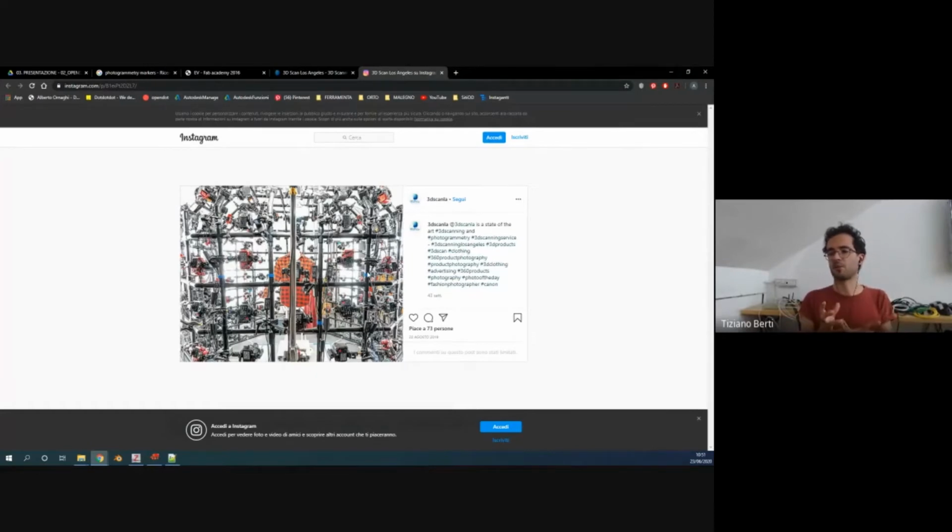If you have an object that is always in the same position while you're doing your photos, it will be much better. Because if you have any tiny movement in the person while doing the photos, this will be an error in the photogrammetry, and the software will not be able to align the photos correctly.